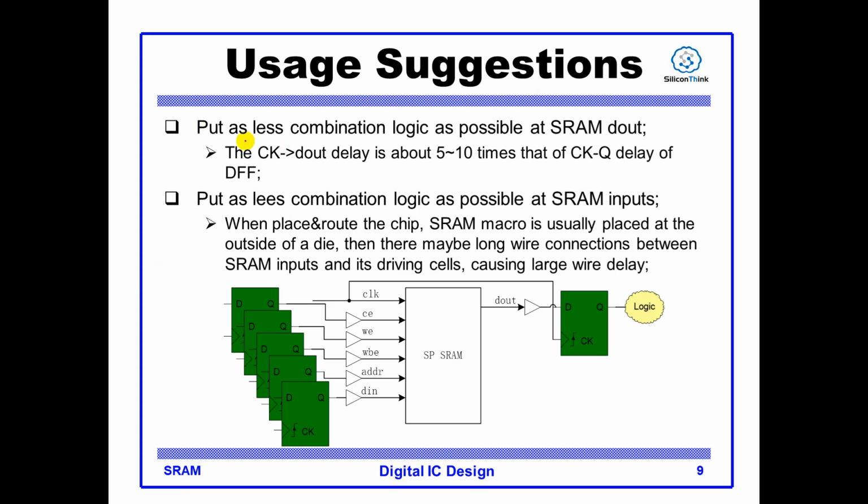And the second is, please put as little combination logic as possible at the SRAM D out point. So please don't put an adder or subtractor here, or many cascaded muxes. Don't put too many logic delays here.